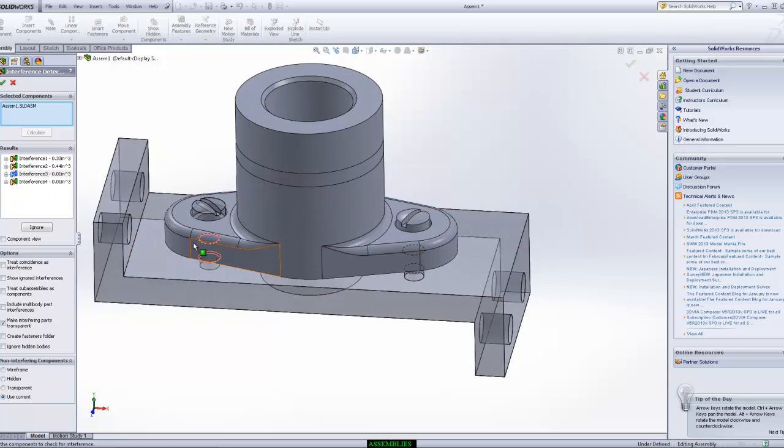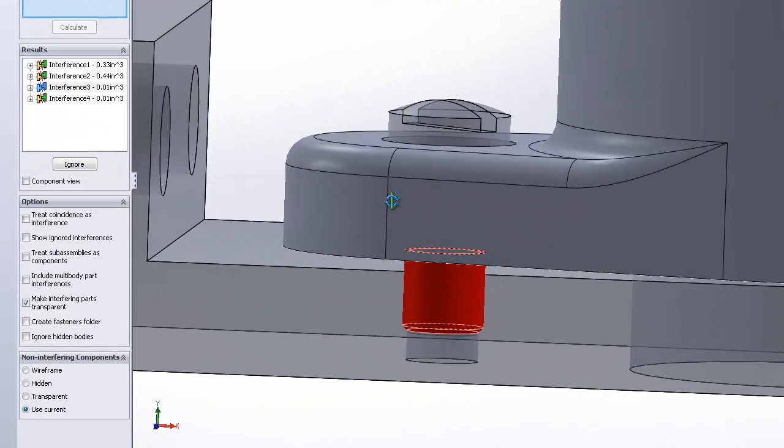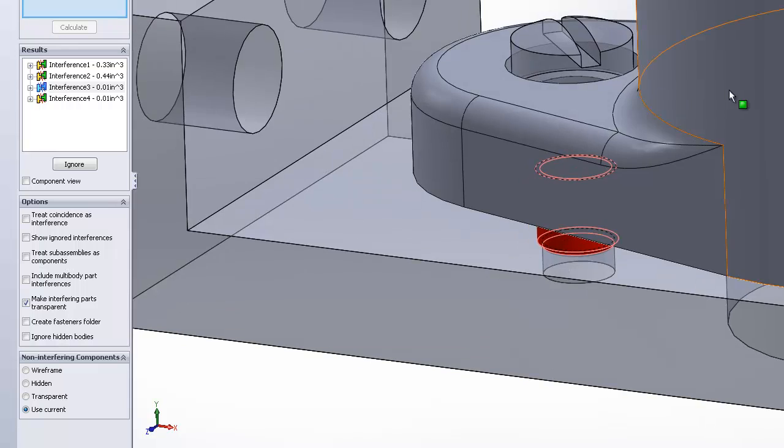After you get this assembled, I will do some more explanation about this, but why is it telling me that my screws are interfering? Because the threads are cosmetic, and the outside diameter of my screw is bigger than the inside diameter of my hole. So it's showing you the interference of the screws. It's like you haven't tapped the hole yet. Correct. It's not been tapped.